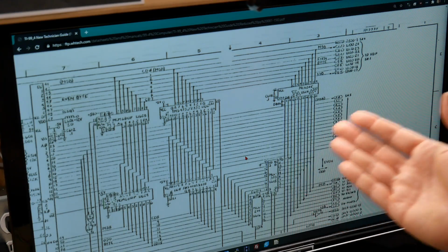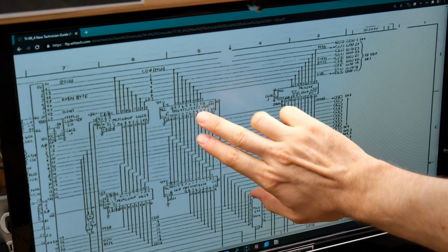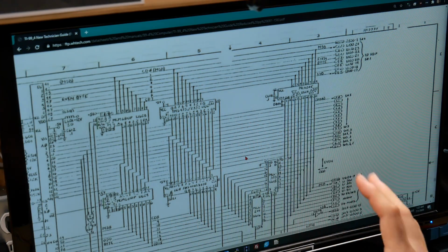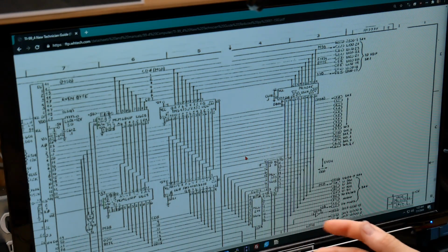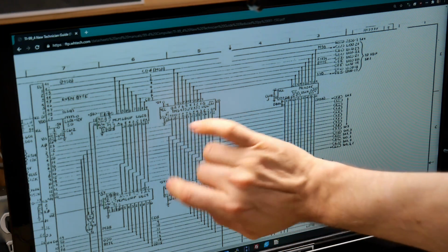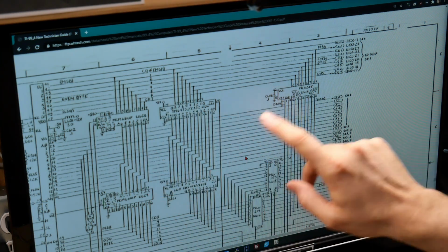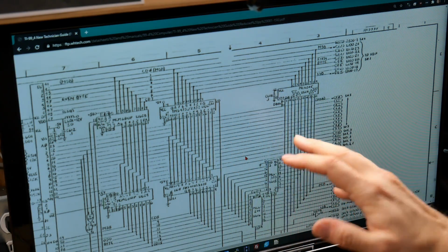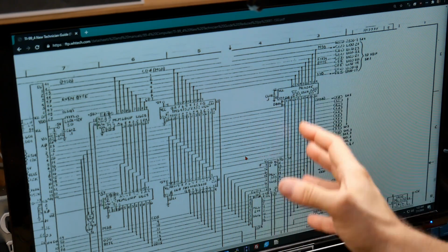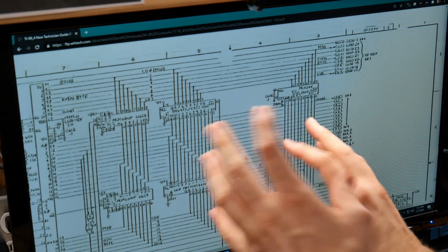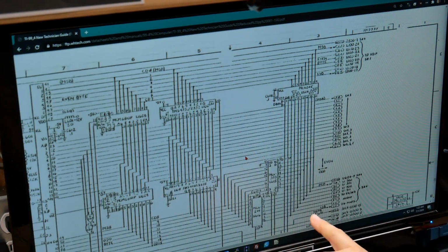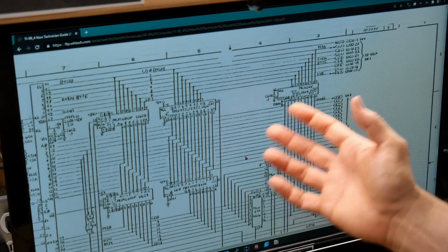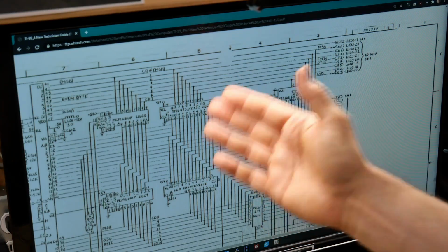There's something called a current tracer, which could help you determine if a chip is holding a line low. It's basically fighting against the CPU, and you can figure out which chip it is with those types of tools. I don't have a tool like that, so there's no way for me to do it. Now, sometimes if things are screwed up, one of these chips will be running hot, right? That's what I did at the beginning of the video. You could touch it if there's a short internally that's causing those lines to short, but clearly whatever fault is going on, it's not all the data lines that are screwed up and they're all connected to all these things, right? It's a couple of the lines that are bad. So at this point, all I can do is start to try to figure out what's bad by pulling chips.